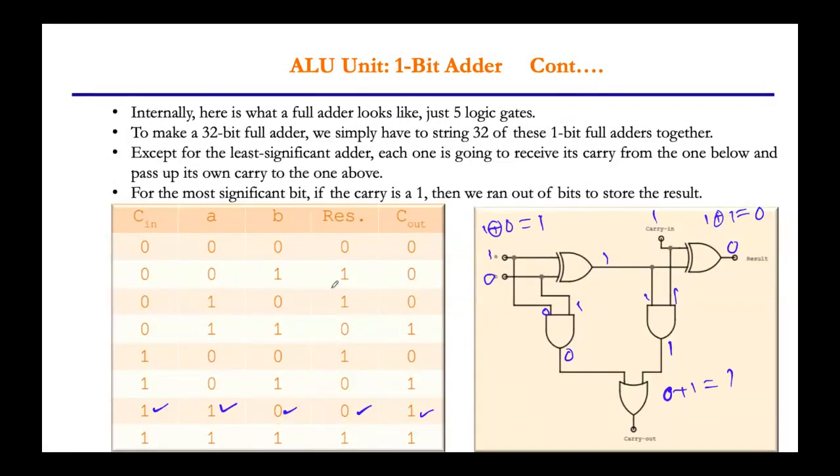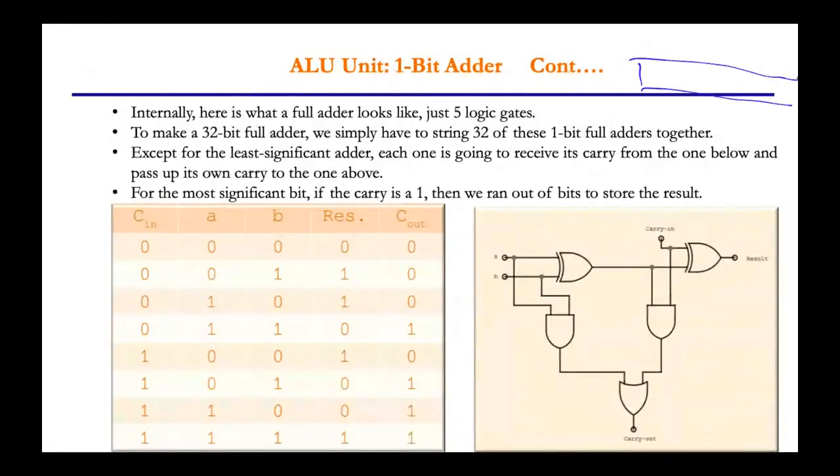So we call this your ALU unit with 1 bit adder. But similarly, if we have 32 bits as we represented in IEEE format, we find the 32 bits, right? In 32 bit, what we use? First bit is your sign bit. Then 8 bits are your exponent bits, and the remaining 23 bits are your fractional bits, right? Fractional part. So total 32 bits.